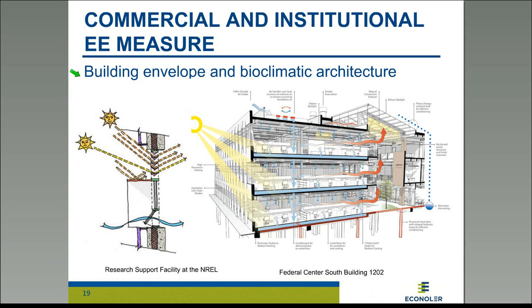So, of course, building envelope is a bit difficult to justify on a retrofit project. If it's just to replace windows or install new walls, insulation, and roof insulation, and try to get a very short payback from those activities, it's generally not the case. It generally takes a longer investment period to implement those kinds of projects. But envelope optimization activities are perfectly well suited for large renovation projects and also for new constructions.